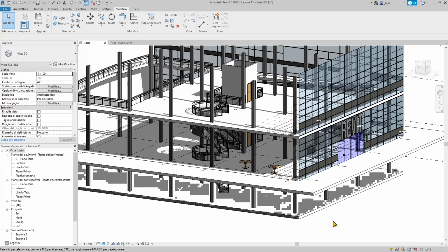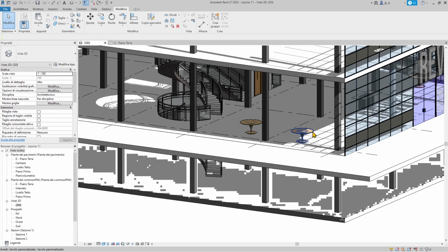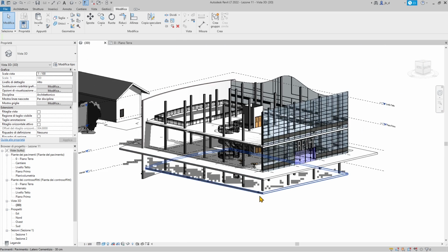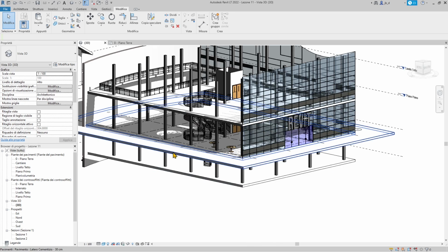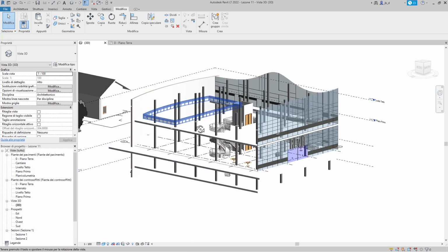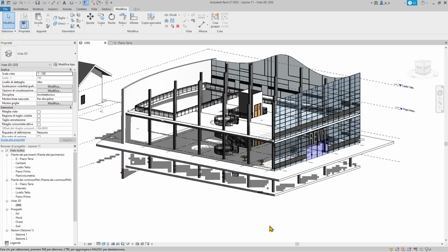We will create new families, and we will see that family creation always starts by creating a profile in 2D, and then from that you will create your model, which is going to be really simple 3D modeling. We already mentioned this in the beginning of the course when we talked about the other software out there to create 3D models. Well, Revit has only a few tools to do 3D modeling. So if you want to do more, you should move into Rhinoceros or Maya or 3ds Max or Cinema 4D and all those 3D modeling software out there. But we're going to see what we can do in Revit.